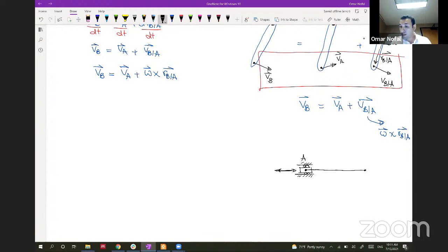And this arm from here is attached to another arm, which is bent from the bottom here. And let's see how this motion looks. So this point is bent, so we call this an instantaneous center of zero velocity. And actually it is not instantaneous, it's a permanent center of zero velocity.